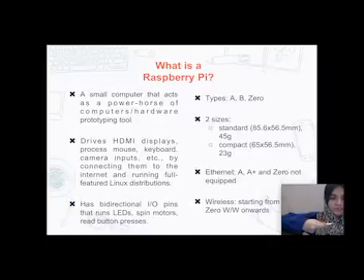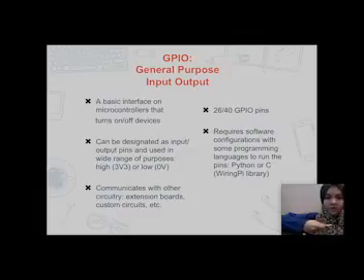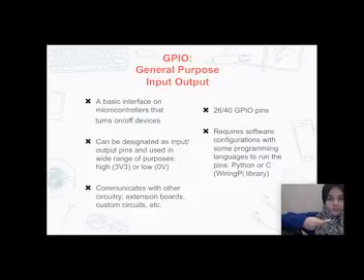However, these Raspberry Pis are not all applicable for USB booting mode, which uses a flash drive. The only ones that are applicable are Raspberry Pi 2B, V1.2, 3A+, 3B, and 3B+. So moving on to the next slide is GPIO, General Purpose Input Output.